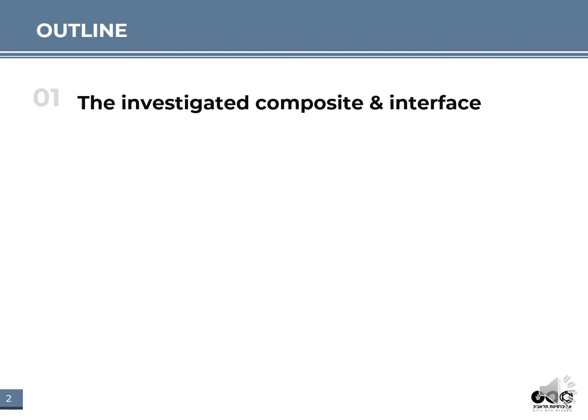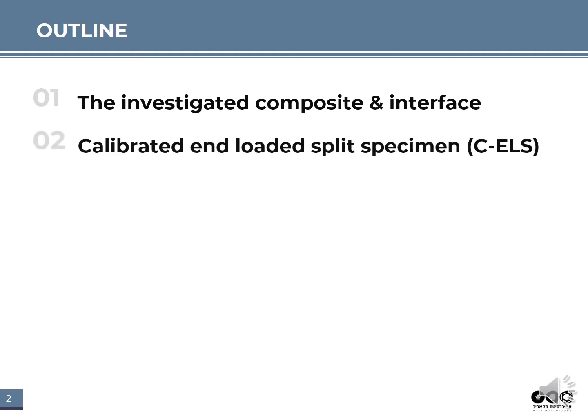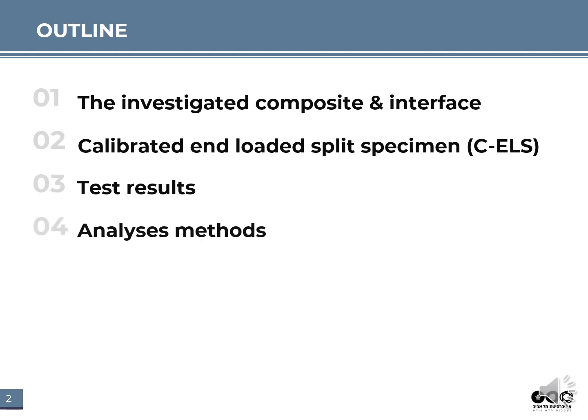The outline of this presentation will begin with an introduction of the investigated composite and interface. The calibrated end loaded split specimens which were used in the nearly mode 2 fracture toughness tests will be shown. Results from these tests will be presented, and the analysis methods which were used in order to obtain the initiation and resistance energy release rates will be explained.